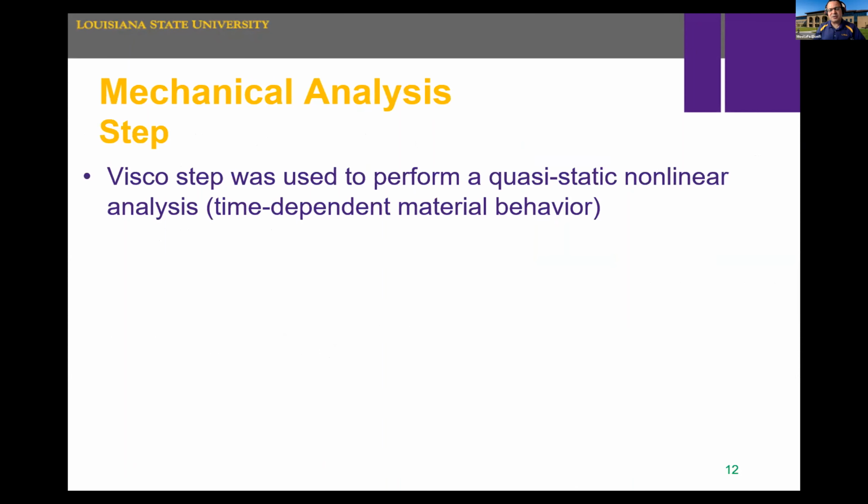So to simulate the process of load movement, we use an approach in Abaqus known as quasi-static. Quasi-static is not a real dynamic analysis, but it accounts for the time-dependent behavior of the material. So it considers the creep behavior and the time delay that you obtain with viscoelastic material.